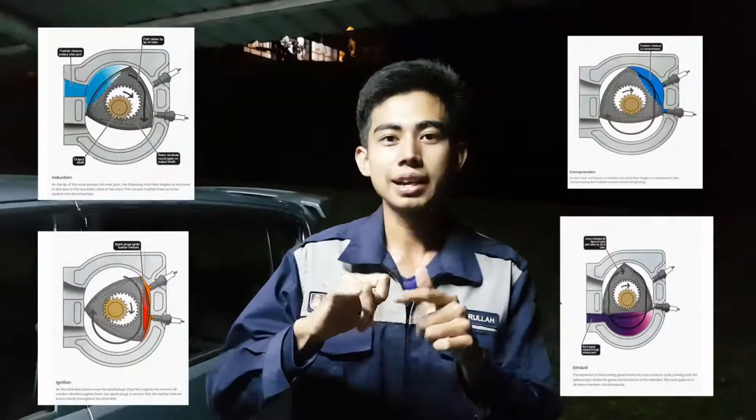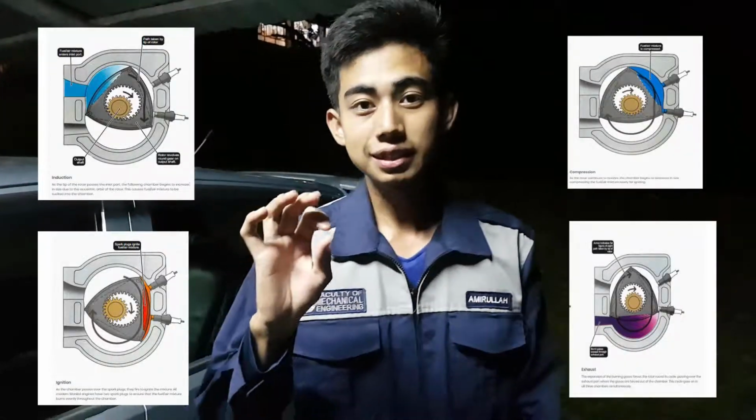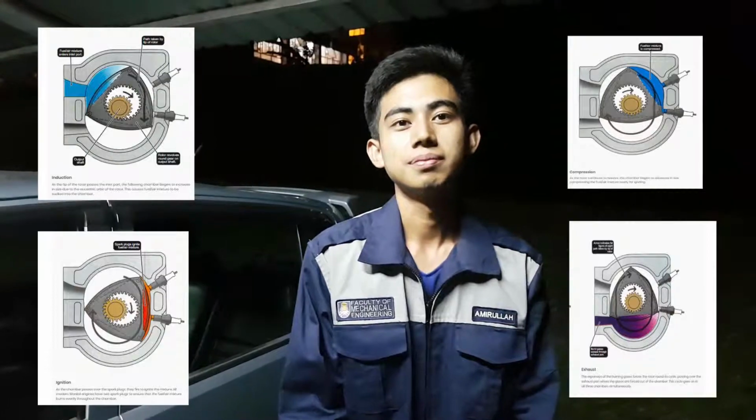Lastly, the principle of operation of the Wankel RC engine. It is an Otto cycle engine consisting of 4 strokes. It has 4 phases in its combustion engine, which are intake, compression, combustion or power, and exhaust. Unlike the conventional piston engine, the fuel air mixture is swept along, so the 4 phases take place in different areas in the engine system.